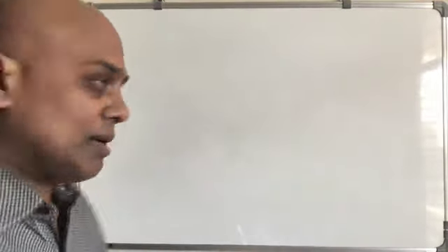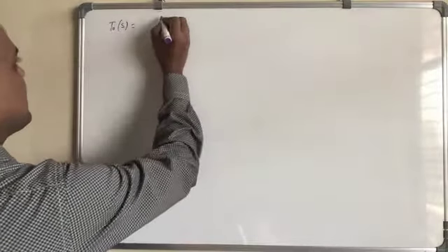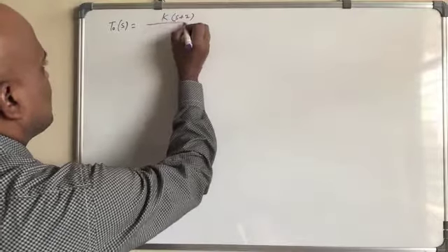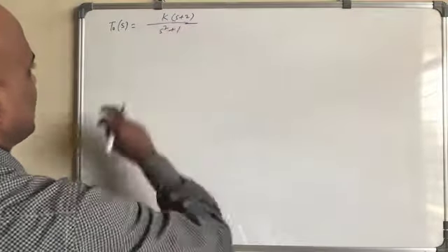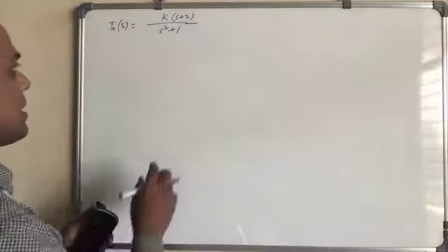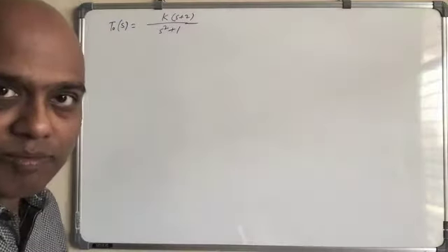Let's take one more example, and the open loop transfer function in this case is k times (s plus 2) divided by (s square plus 1). So this will have a complex root, but we also have zeros here, so it is a little different from other problems.